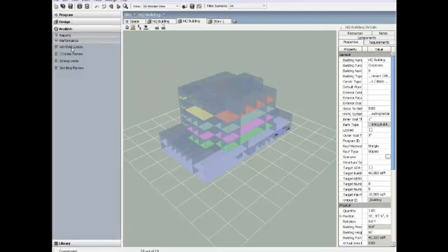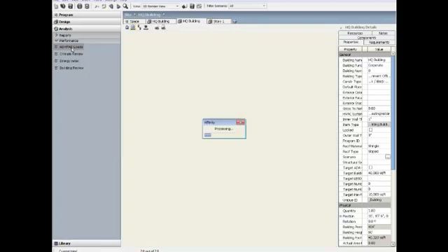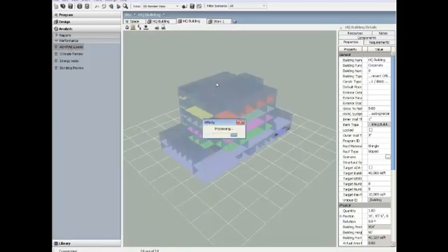ASHRAE allows me to understand the heating and cooling loads for the building and individual rooms using the ASHRAE 2005 heat balance method. There is a section in this report that allows us to focus in on the room level. It's actually interactive and allows us to set a target criteria and view any of the exceptions room by room. With a number of my windows open here, it's taking a bit of time to open this up, so let's actually come back to this section.